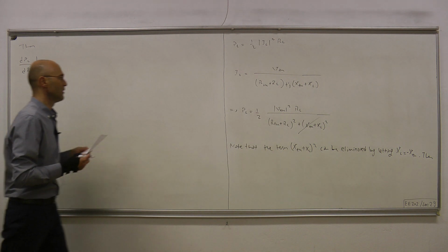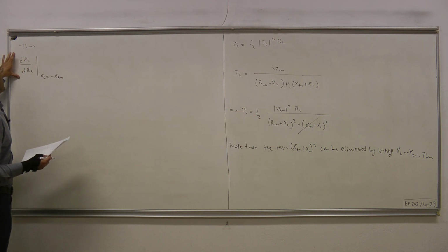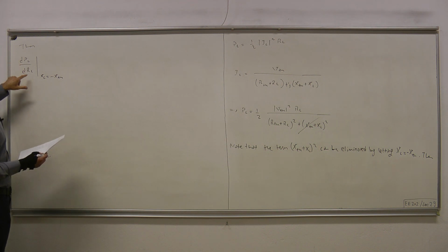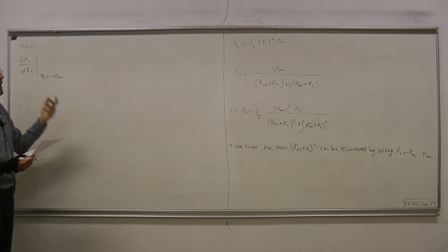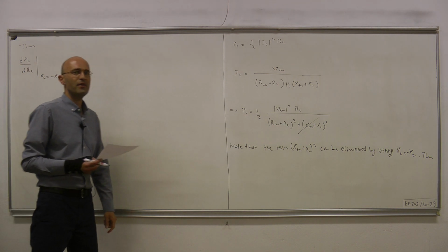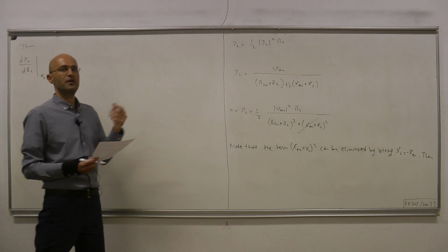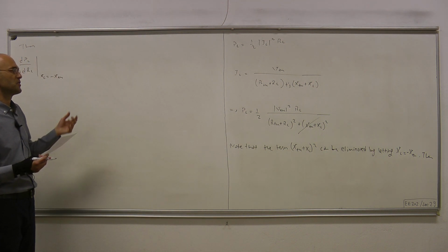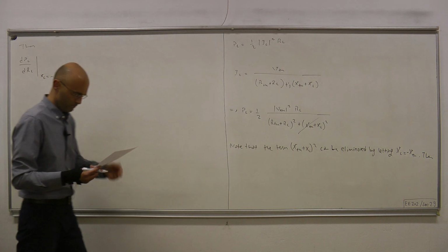What we do is, because it's not obvious, we differentiate it with respect to our now only design variable RL, because XL is already chosen, and then equate the derivative to 0. We know that whenever the derivative is 0, we're either at the minimum or maximum, and in this case, this will give us the maximum for PL.